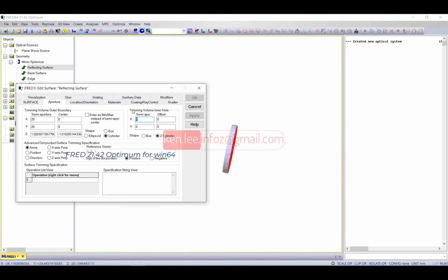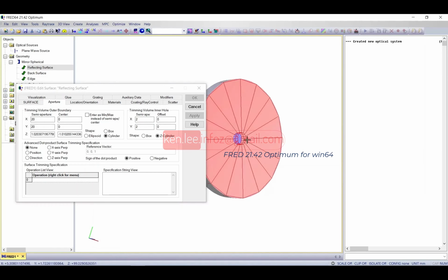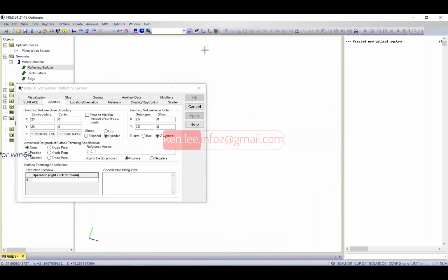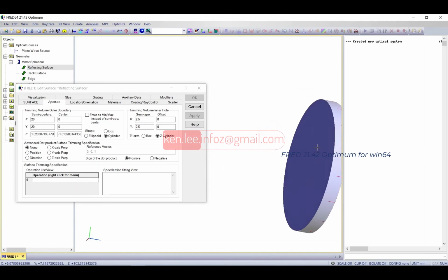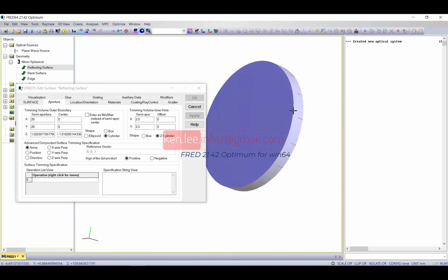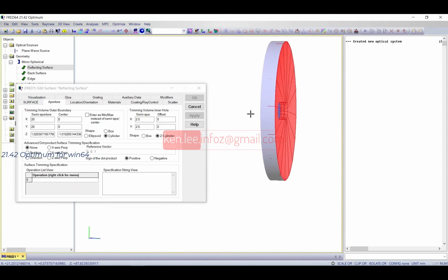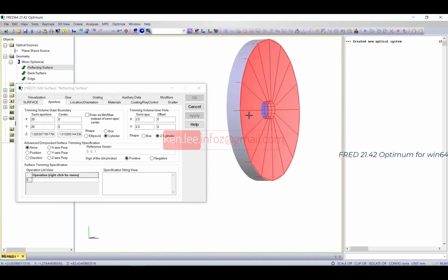I think our plane wave was something like 2 millimeters times 2 millimeters. So I will give it 2 millimeters times 2 millimeters size, maybe even 2.5. And then you can see that there is suddenly a hole on it. Unfortunately, that's only on one side. So this works with surfaces. That's not a bulk element really. It's just surfaces and surface boundaries.